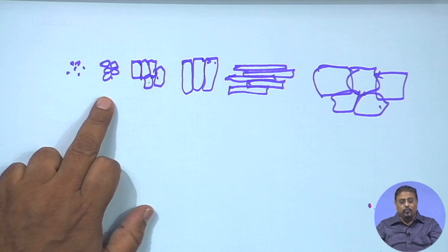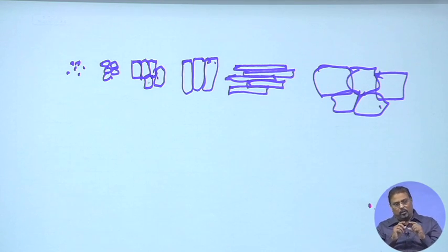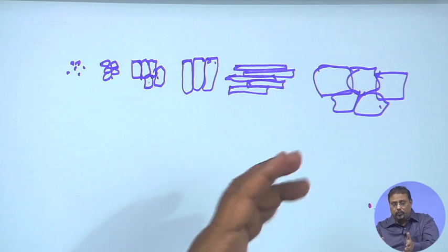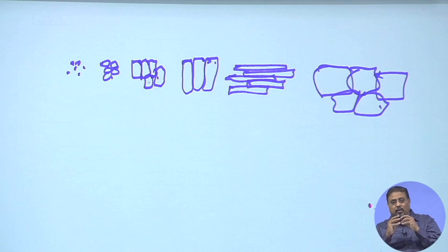Okay, and then if you find it is not that dusty, but still there is a layer of dust, then you should understand there is a granular structure, but at the top surface, because of the wind erosion, the granules have been further broken, and they become small fine granular, and the top layers are flowing out. But overall it does not look very, very dusty. When you look at the blocky one, if you take 1 foot by 1 foot by 1 foot, 1 cubic foot of soil, you will find that the sizes are not very large, and they are almost cuboid kind of things.